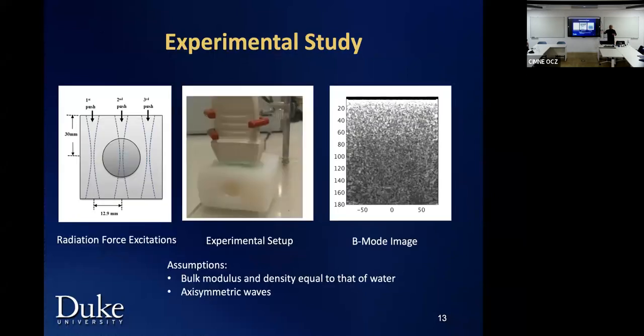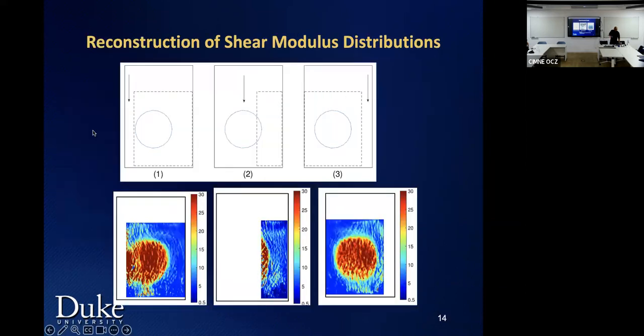Okay, now, let me show you an actual problem that we solved with this, with experiments and everything. So with Mayo Clinic, we've been working on imaging elastic moduli. Here is where the bulk modulus disappears, because now it's known. We give it as a known to the code. We just solve everything in terms of shear modulus, but it's not known everywhere, right? Or it's nowhere known. The experiment was what you see in the middle here. I have a gel with a harder, stiffer gel in the middle. Have the transducer here, and there are 3 sets of experiments where we drive.